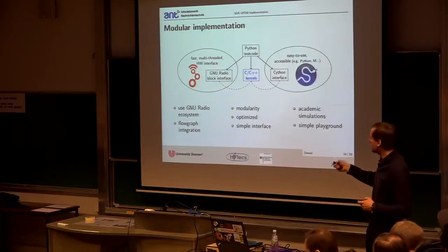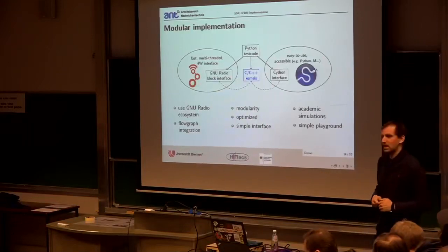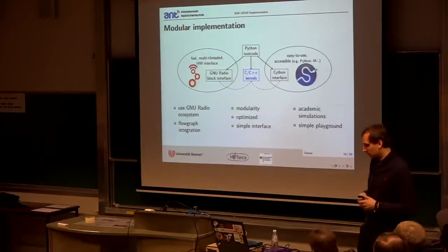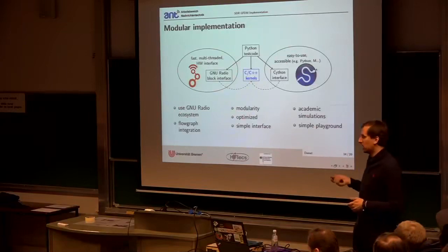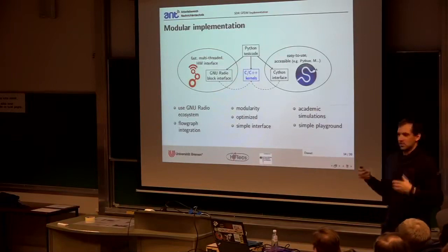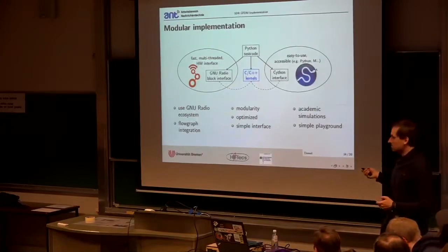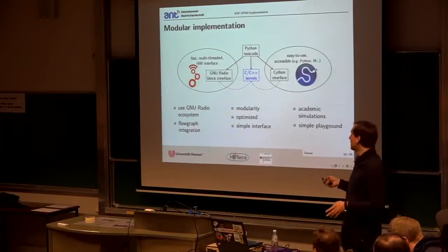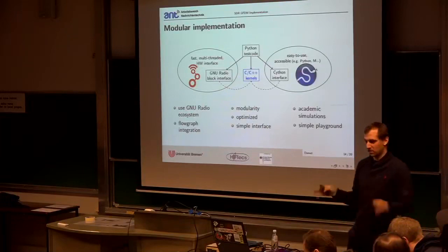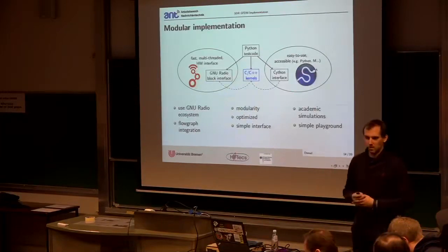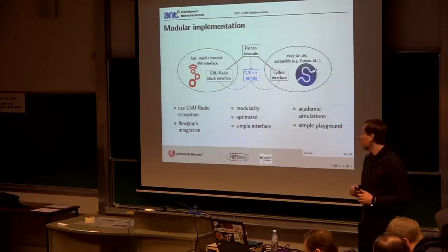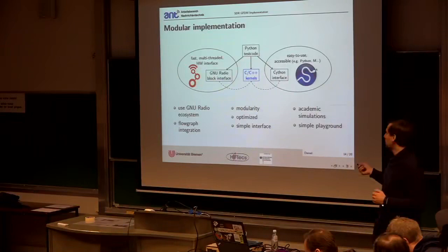And then on the other hand, you can just plug that into your GNU Radio block structure, just call the appropriate functions, pass around the pointers, and just use all the benefits of GNU Radio, like it takes care that everything runs fast, that it runs multi-threaded, that you have your hardware interfaces, you don't have to worry about that. I mean, no one wants to rewrite any drivers or things like that. So that's the general idea of how we split our software into different components.